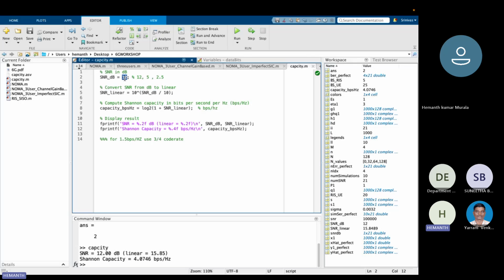For the same example, I will put 5. This is the worst condition. I am entering into the room, so my device receives only 5 dB. Then tell me, what is the capacity here? 2. 2 means which modulation scheme can you choose? QPSK. So 2 into the bandwidth, which is 100 megahertz, how much data will be supported? 200. So these are the things according to your SNR.